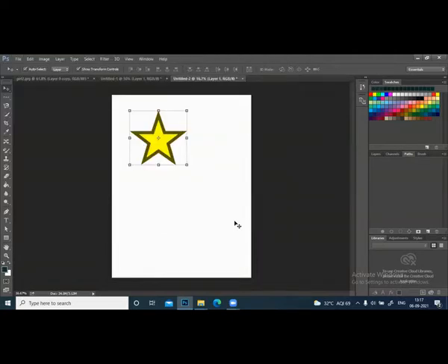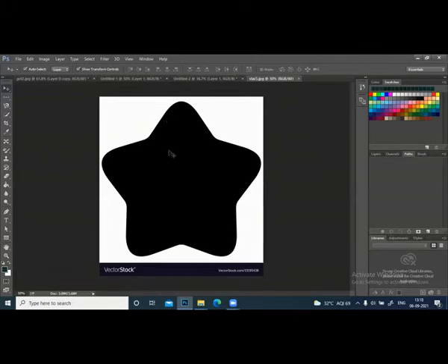This star, I'm having some curves. So I will go to pen, I typed P. Hit the first point. Second point, slowly drag. Now if I click, it will be a curve. I want a straight line. So I have to remove this handle. So I'll press Alt and click the main anchor point. Click. So it removed that. Now it is very easy. Click. Straight line I got.